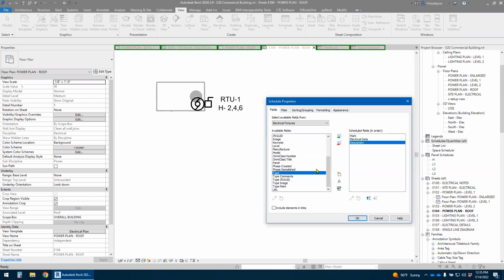We want type. We want to put the panel. We want to put the circuit number with it. Heck, let's give it what floor it's on. We can issue that information. And even if there's comments, this is really going to be a key location. This description, remember, if we put in the description the words mech equip schedule or something like that, that's what I'm going to use here now in a moment.